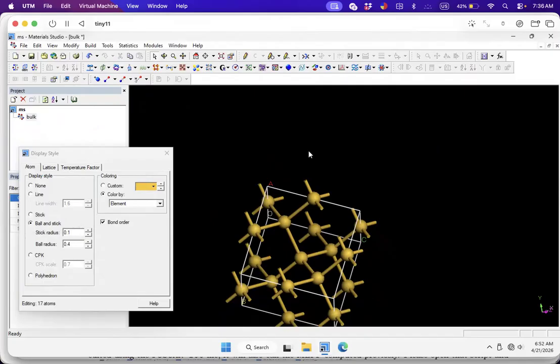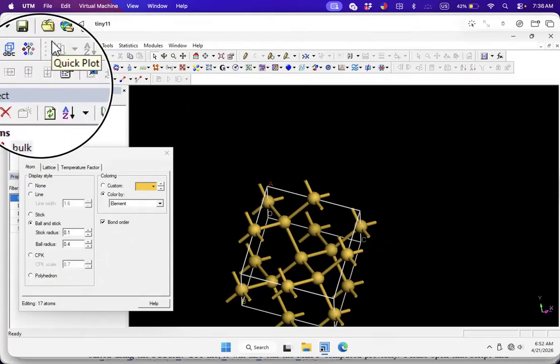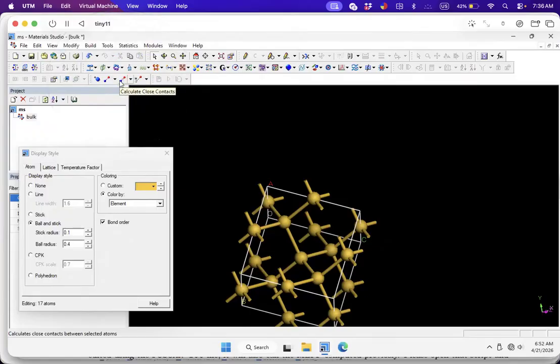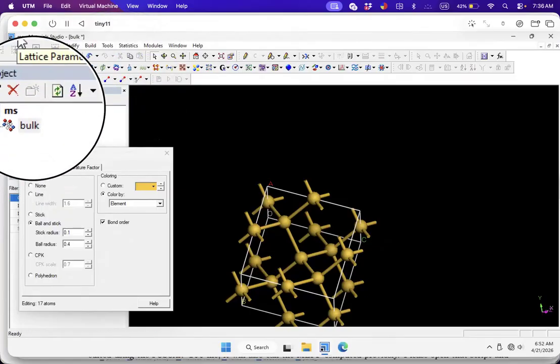So you get this structure. If we apply symmetry, this program will give you automatically the unit cell. Now, since I need to orient it in a proper way, I use this, please, here. First of all, we go here to ABC, in lattice parameters.